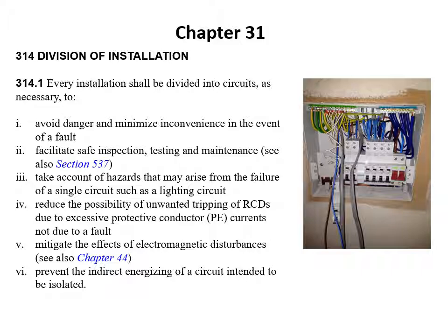And the other advantages with splitting into multiple circuits is, of course, it reduces the possibility of unwanted tripping of the RCDs due to excessive protective current in the protective conductors. And we can also prevent indirect energizing of a circuit that's intended to be isolated.